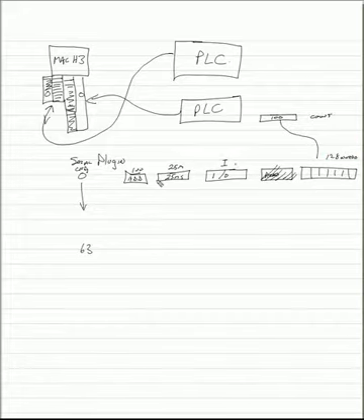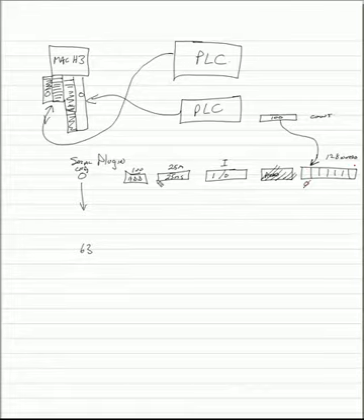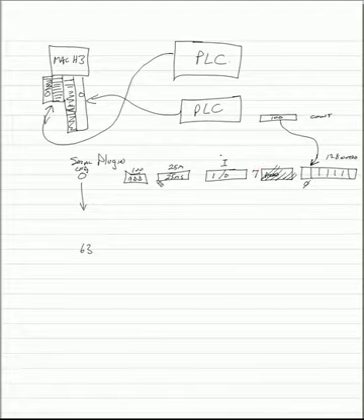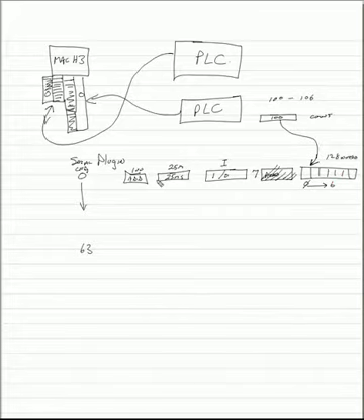By default, every time you transfer something into a configuration area, the first register goes into word 0 of the 128 words. If you tell the configuration that you're going to transfer 7 registers, and you started at address 100, then the PLC will transfer from 100 to 106, that's 7 registers, and transfer them 0 to 6 inside this area.